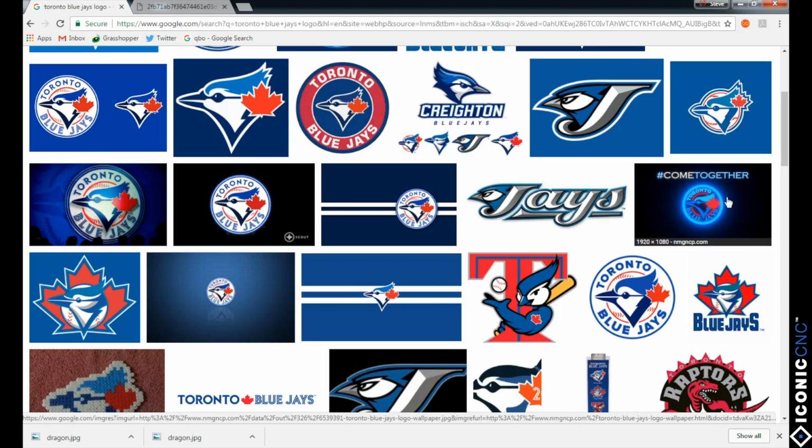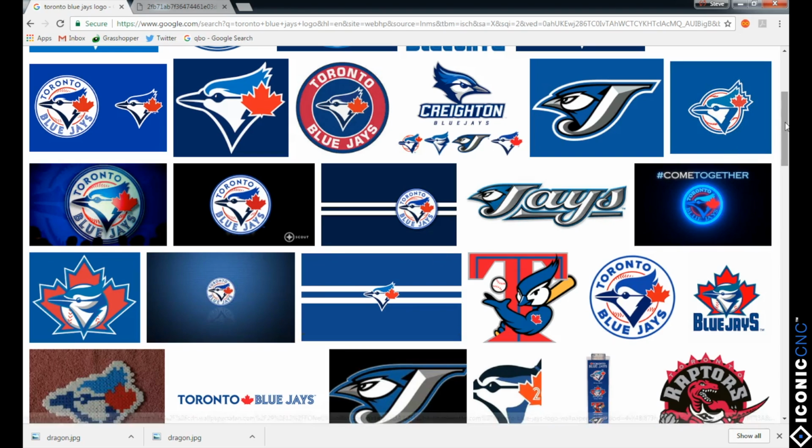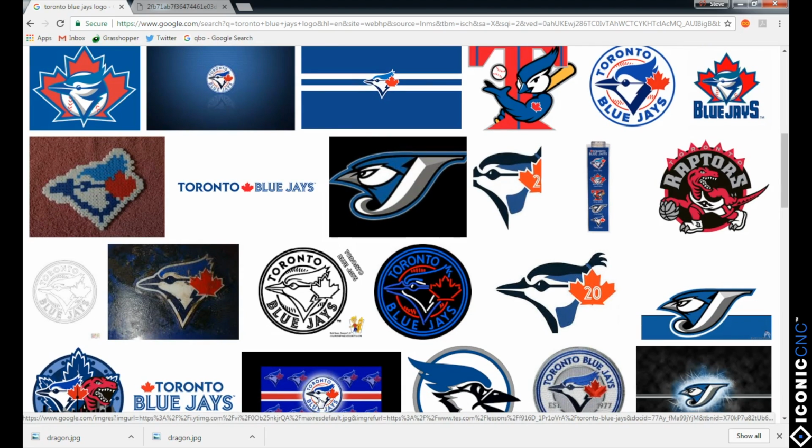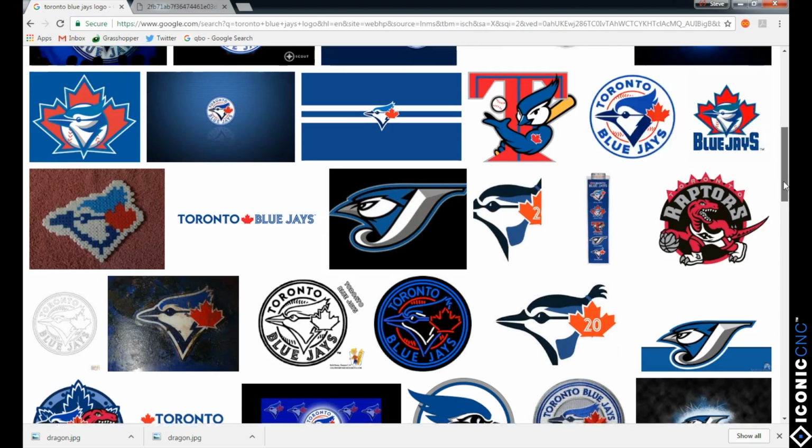Essentially what the software is going to do is create tracing lines around the image so that we have clean machining lines, and it won't know where to draw those lines. You can see this image here also possesses that same problem. So anything that has that gradient or graduated screen, like this one down here, this one, would be images that you'd want to stay away from.